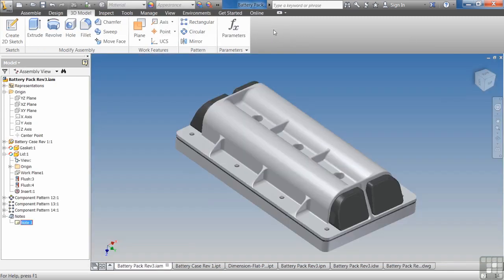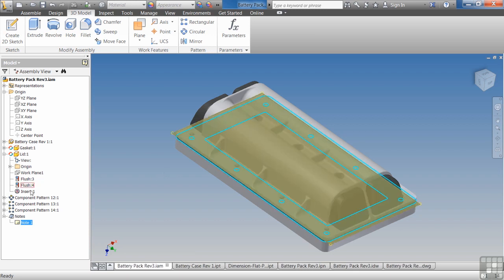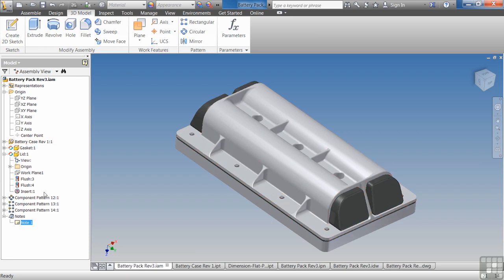And you can see that there's a lot of information in here. And so Inventor likes to break it up into these individual files. No file is more important than the other, but that relationship is important to Inventor. So you want to make sure you don't move these files out of the project file. Everything has to reside under that project file. And if you do lose a component, you will notice the browser will give you some kind of little funky thing basically saying, hey, I can't find that component, and it wants you to go find it.